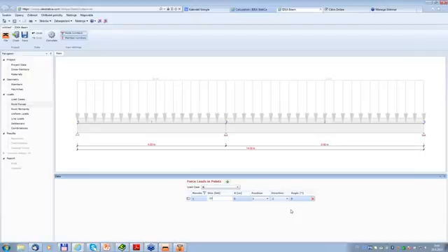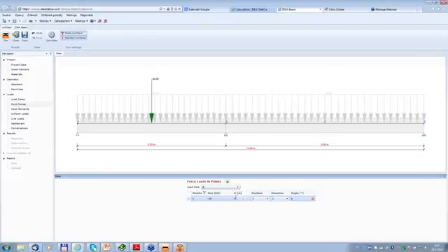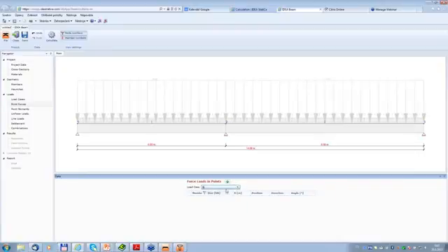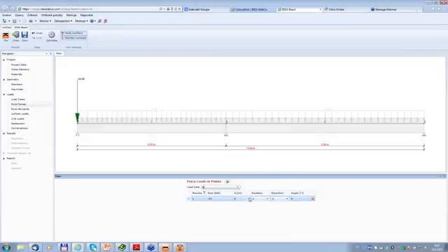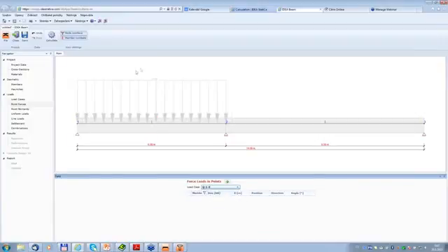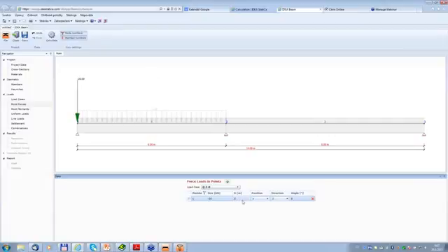I can define point forces, which I do because it was the task in this example. So my force will be minus 30 and it will be in member 1 in position 3 meters. You can see now for live load or variable load, as they say now in Eurocode, we can define minus 20 force in 3 meters, and this I have to input also for this load case. When the first span is loaded, then I define the same load in 3 meters.